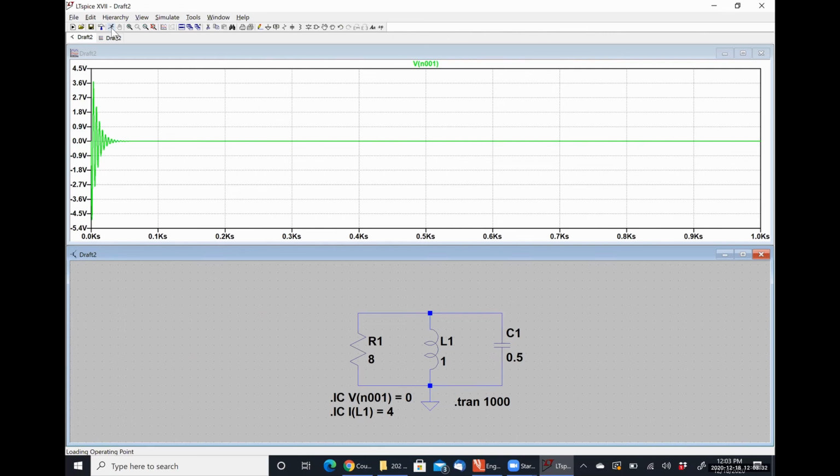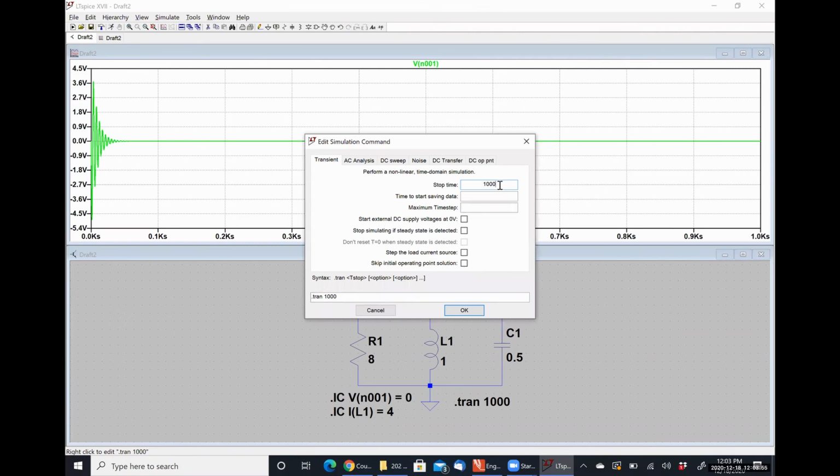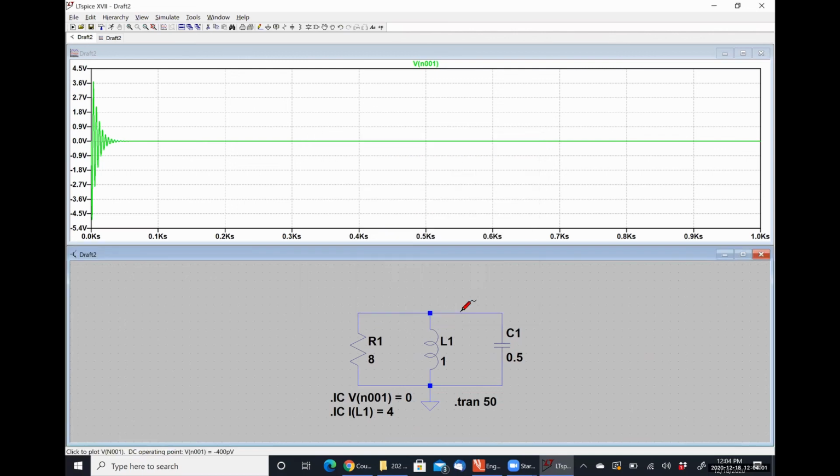So 5 or 6 time constants should get me settling really close to the final value, somewhere between 40 to 50 seconds. If I had done the math correctly the first time, I wouldn't have had to iterate, but I wanted to show you some stuff anyway.